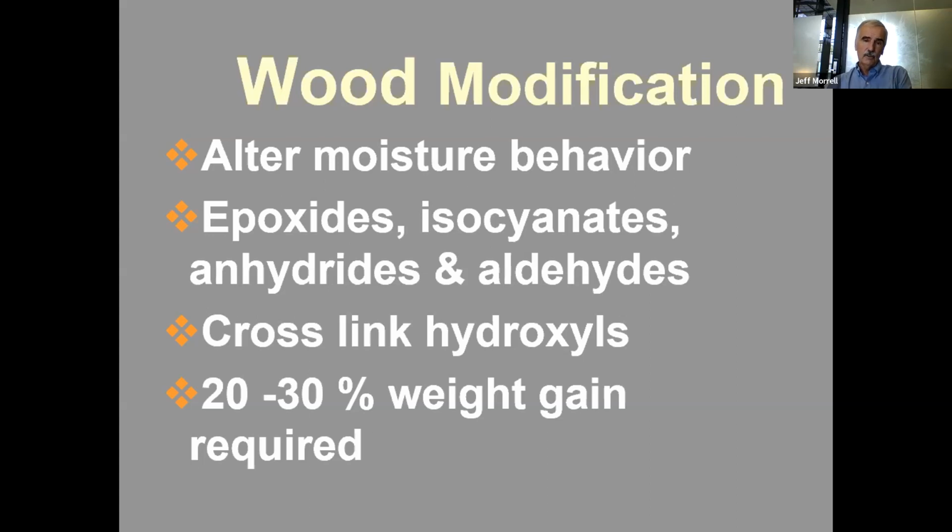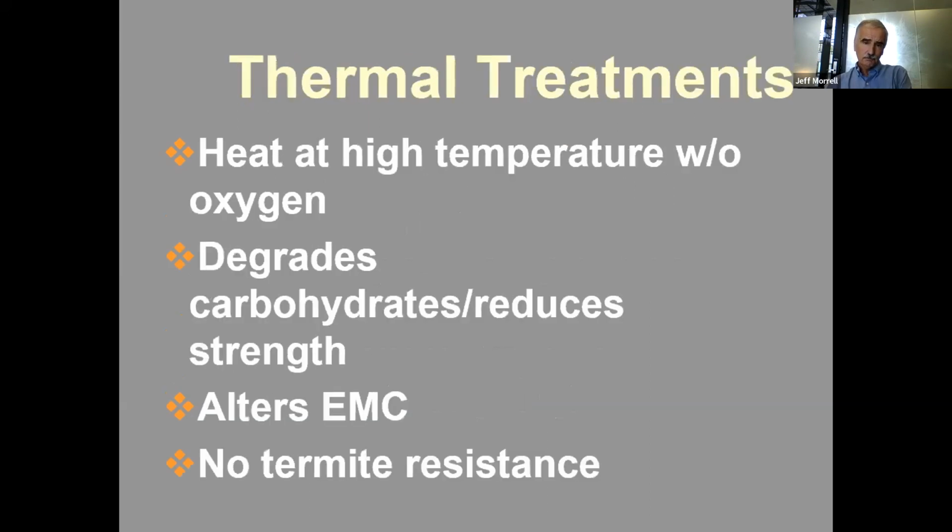We put a chemical in that changes the water behavior of the wood, and it makes the wood less reactive to, or less susceptible to, decay. You're seeing a lot of that in Australia. It has performed well, particularly above ground, but we also have some work in marine environments where it's done well as well. There are thermal treatments, which are also coming in.